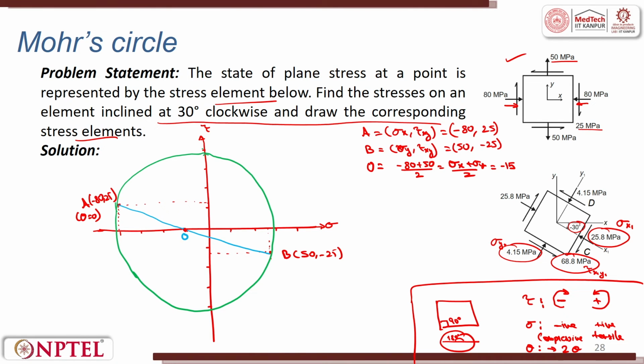So here the angle given is now 30 degrees. So 30 degrees, as I have given it to you, the theta becomes 2 theta. 2 theta is equal to 30 degrees clockwise is given, so I will put it as 60 degrees. So at an angle of 60 degrees from here, I will draw a line. So this is 60 degrees, or you call it minus 60 degrees from there in this direction. And this is our theta, it is given theta 1.